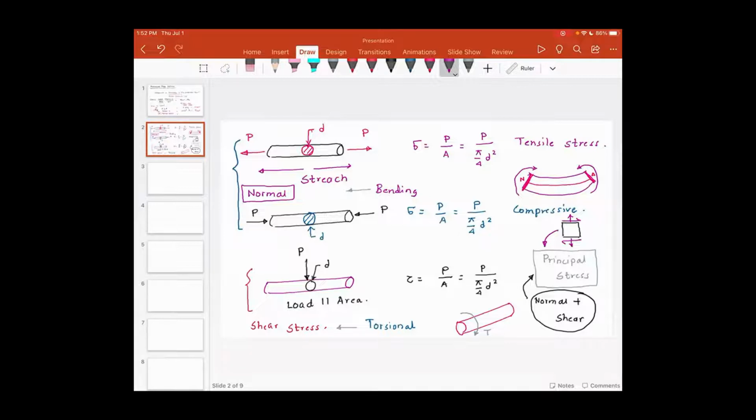The reason is that 45 degrees is the weakest plane for aluminum, which means even though your loading is axial, the stress induced on the 45-degree plane is stronger than the material can withstand, and naturally the material does not know whether the stress is bending or torsional.